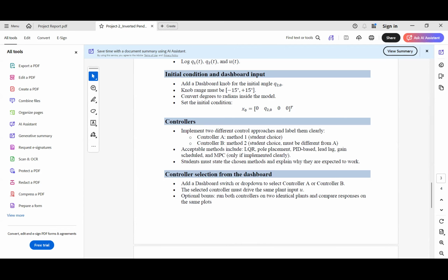The switch block here is created to filter the value, whether we are choosing the LQR or pole placement. This will give you one value, and it will go into the MATLAB function. We have created the actuator here, and we have given it the value of -20 and 20. So the maximum value the control force will give is 20 and -20. The actuator value will go directly into the plant, and all the values coming from here will go to the plant.